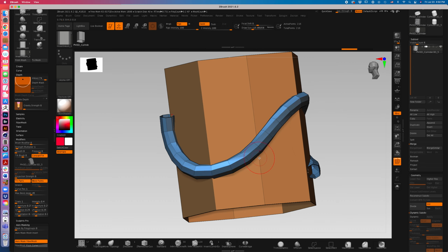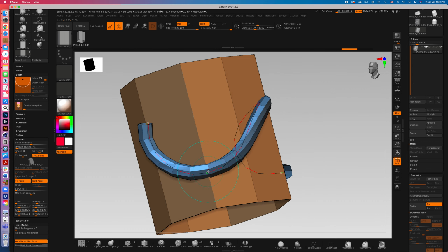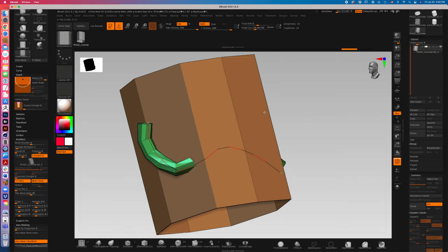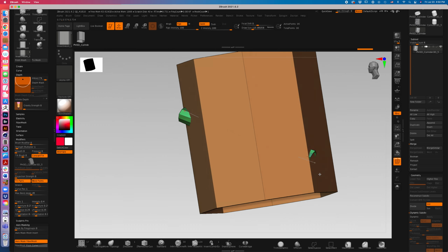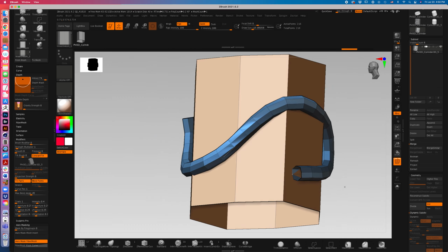You don't really want to do that generally at this point. What you might want to do is smooth the path. The way to do that is to click on the path first, then hold down the Shift key, and now you can smooth the path, and it will eventually smooth out until it's a straight line between the two points. Also not very useful, but it will be later on.